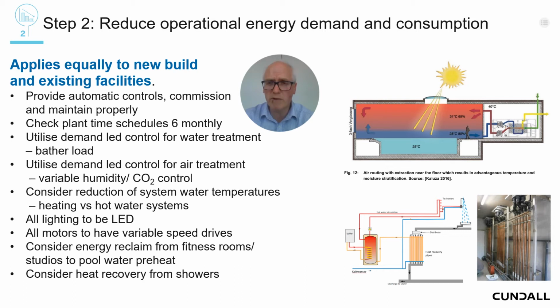And we find when we go to look at existing facilities, it's the operation of the controls, the time schedules, and the operator's knowledge that are usually the things we need to pick up on, and savings can be made just by getting the installed systems to run properly. Then you can build on those and enhance them with variable speed drives, with LED lighting. Pool covers we'll not talk about because we could spend all afternoon on that.